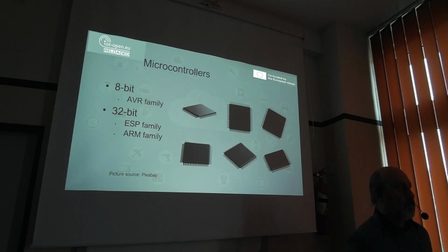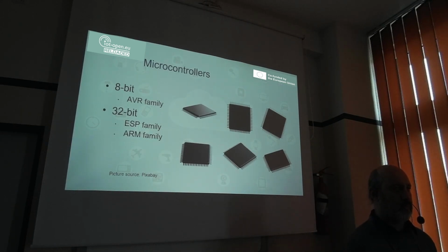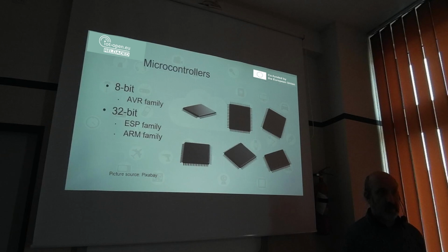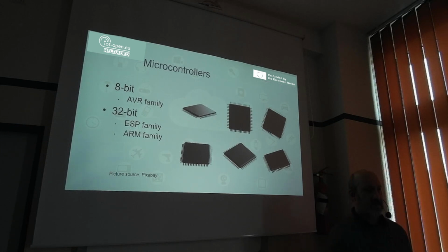We can say that almost every embedded system, IoT node, needs some microcontroller or microprocessor. But usually, in the modern world, there are microcontrollers, and we can have different families of microcontrollers, starting from 8-bit AVR microcontrollers. They must be equipped with some additional networking module. We can use some 32-bit microcontroller like the ESP family.